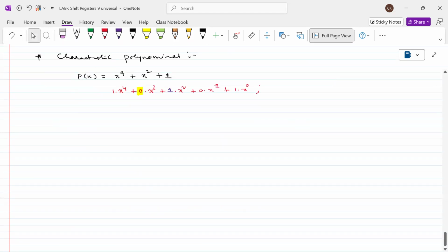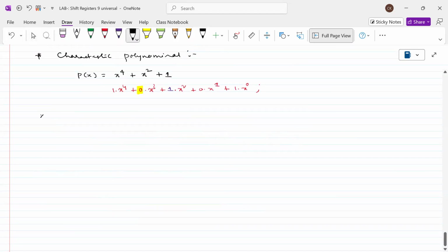One important point you have to remember here is that we should load some data into the registers, right? Okay, we should not load the zero zero pattern in the LFSR. Okay, we should not load all zeros into the flip-flops of the LFSR. If we do that one, forever you will stay in that particular sequence.